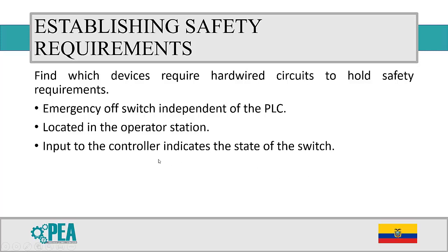And you will have an input to the controller that indicates the state of the switch. In spite of being independent from the PLC, you still need to have feedback to the PLC so that the operator can see that this action has been performed.